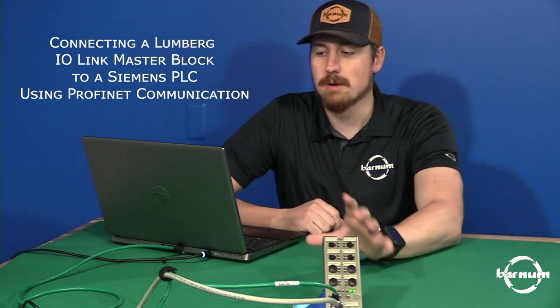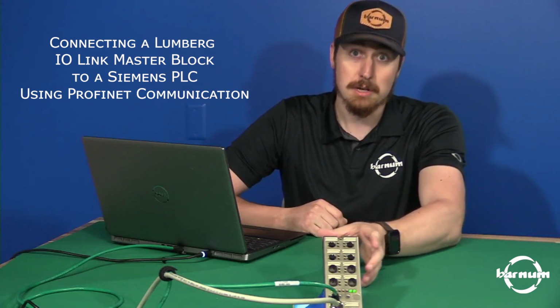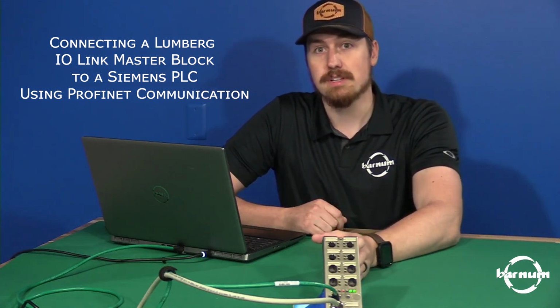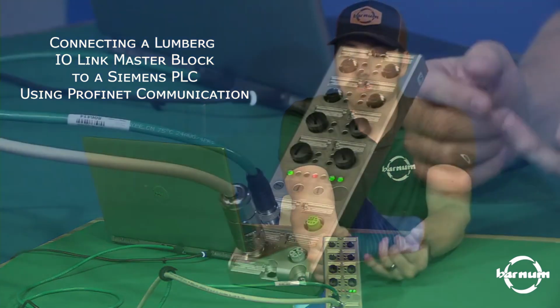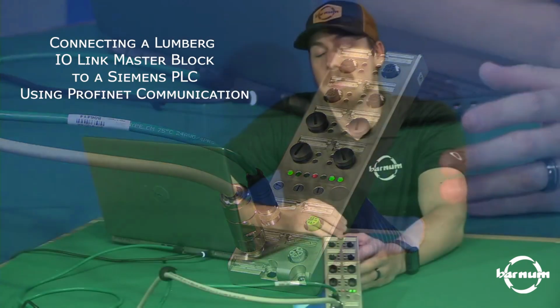A new block coming from the factory can be set to the desired protocol with that rotary switch, but if this is a block that's already been used or you're unsure, the first step is doing a factory reset. Take those rotary switches, turn them to 979, do a power cycle, that will set this back to factory defaults.